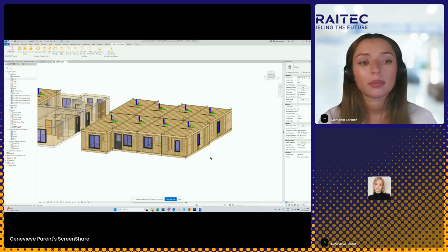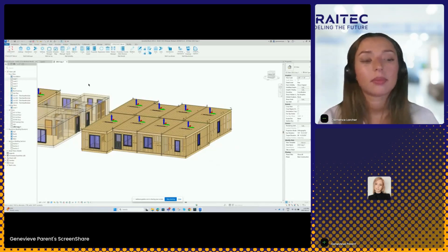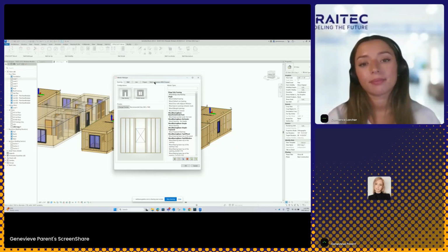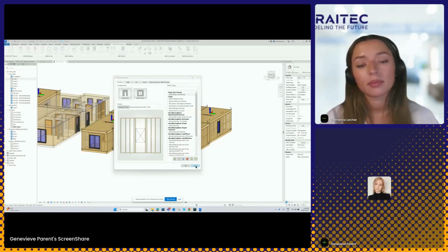If I open up our list, you're going to see it looks a little bit different, and we don't have the same bearing markers. So where you can use the built-up sections in the bearing portion and use that within your opening markers, we don't have that option in wood at this time. But yes, in light gauge steel, if you're already using those markers within that list, it'll be the same thing. So they will be used.